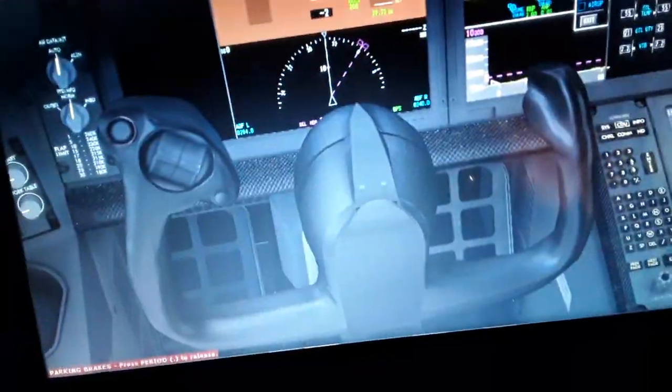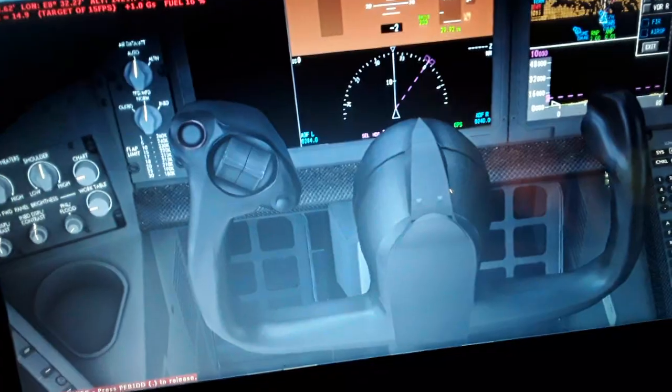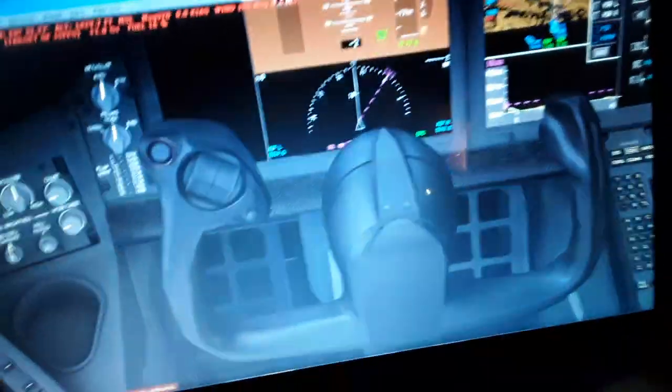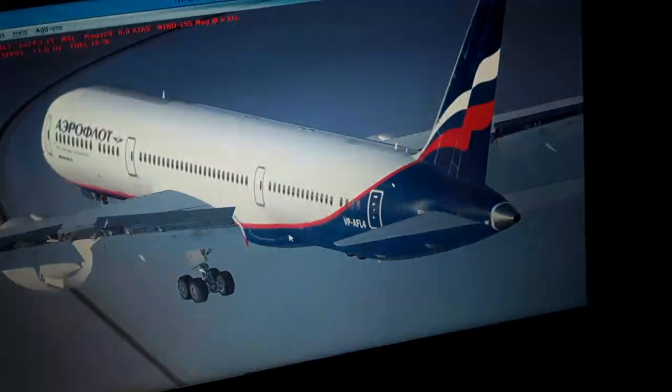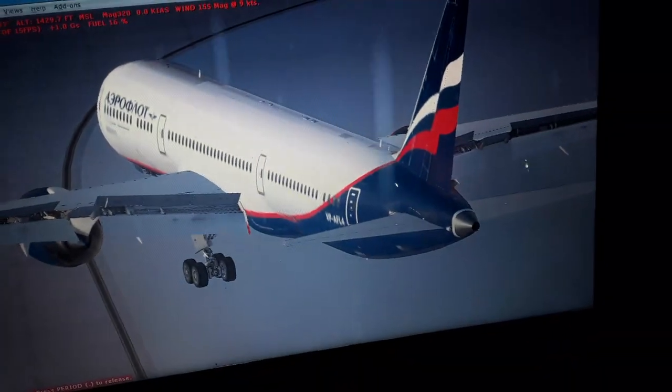We move the thrust levers forward and aft, change the position of the thrust. The FADEC produces the necessary thrust, gives the command to the engine. So you can see here we have the horizontal trim stabilizer. This switch controls the horizontal tail of the elevator for climb or descent, for pitch up or pitch down.